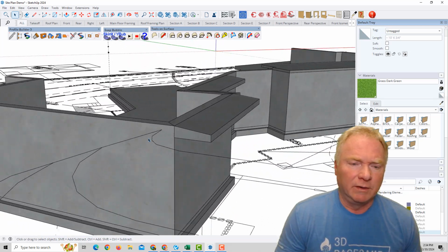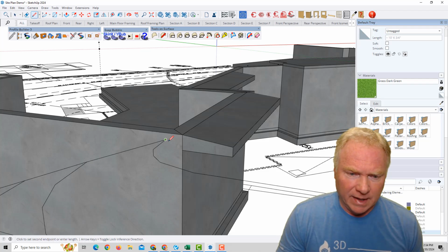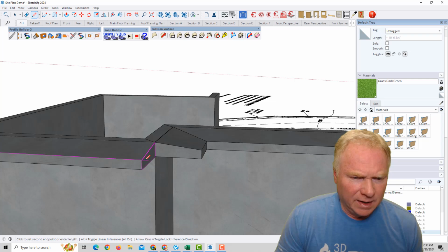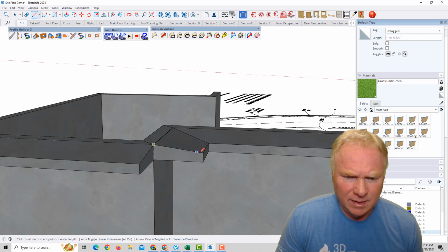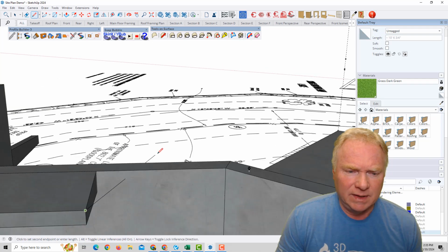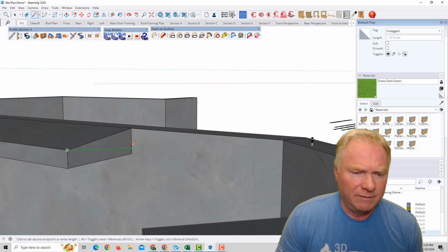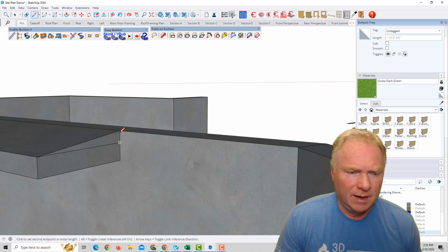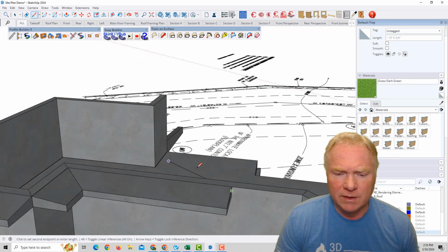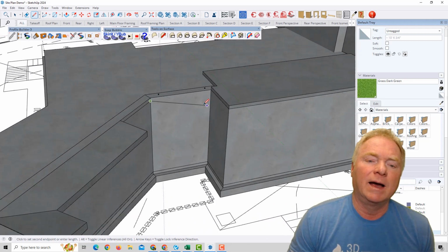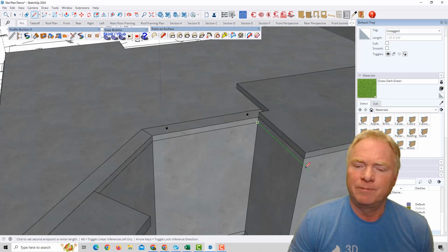All right, so I'm literally going to draw the backfill line. I'm going to go up to this apron and just sort of hug the apron. A lot of fall to that sucker, but now when I get to here, this is getting to the foundation of the house. I can't be any more than 4 inches below the, yeah, that's right at 4 inches. So 4 inches is my minimum for my backfilling. I can't be any higher than 4 inches up on that foundation.